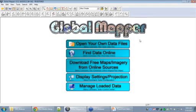We're going to be taking a look at working in the 3rd dimension in Global Mapper. So we're going to be looking at both our 2D top-down mode for interacting with things like terrain models, contour grids, and LiDAR data. We're then going to take a look at that same data in our 3-dimensional viewer, where we can pan, zoom, and rotate all around in the 3rd dimension to interact with the lumps and bumps in that terrain model and all those different types of data.